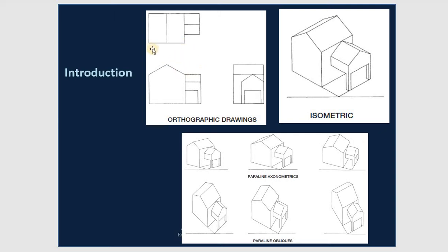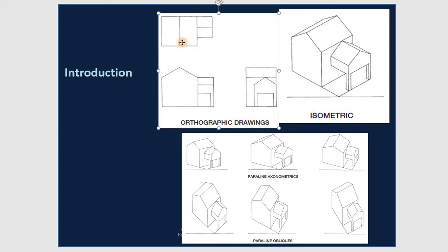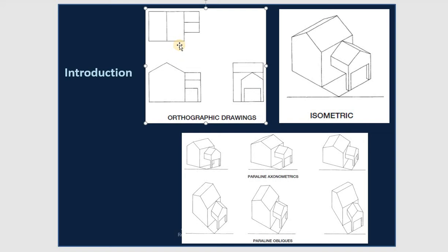You project lines like this, they call that construction lines. You can see the ridge is right here, the highest part of the house. When you draw an elevation like this, you call that orthographic. That means you look straight directly at the building and you draw like this. It's 2D, that means you see the height and the width of the project.